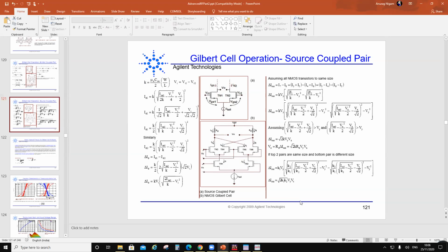Is it easy to implement the Gilbert cell using CMOS in a sub 100 nanometer node? We are scaling threshold voltages also with the supply voltages. So there should not be a problem because the overall voltage scheme will come down. VDD will go down to, let's say, sub 1 volt, and threshold voltages are scaled to like 0.15, 0.2, right? So it is not really going to hurt you because you are scaling VT also with this. The problem is the leakage. So I hope I have answered your question here.